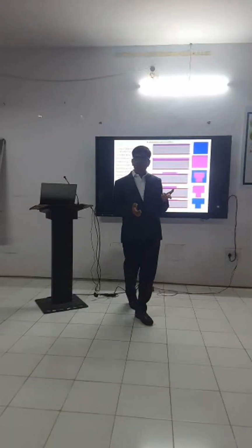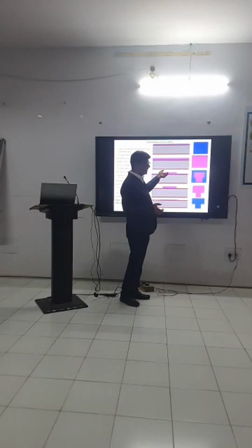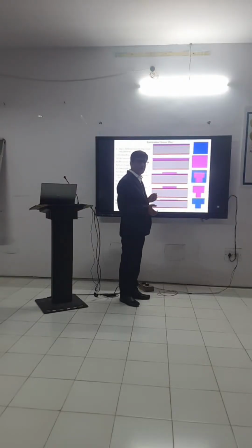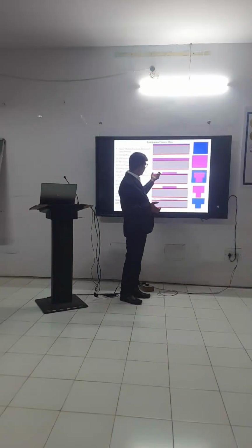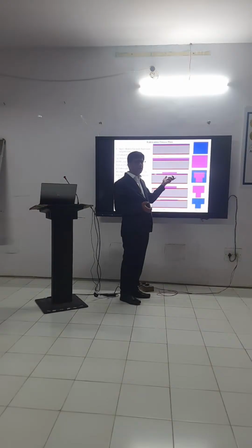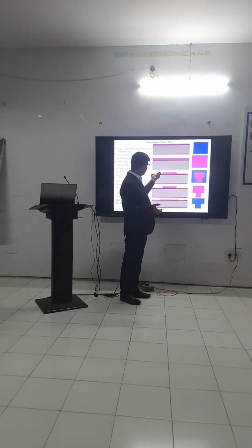Unexposed area of your photoresist will be intact, and exposed area photoresist will be developed in a developer. So now you have this photoresist left, and your nichrome layer will be open in this area and this area, and this photoresist will be creating a masking layer for your nichrome, because this nichrome we want to protect to make my heater, and we want to remove this nichrome and this nichrome to pattern my device.